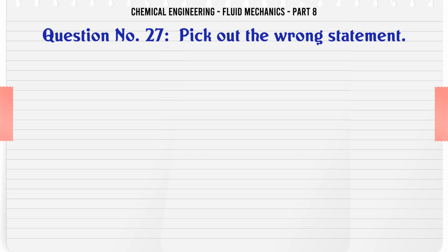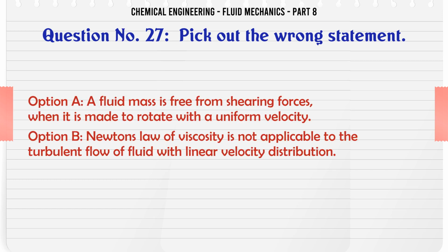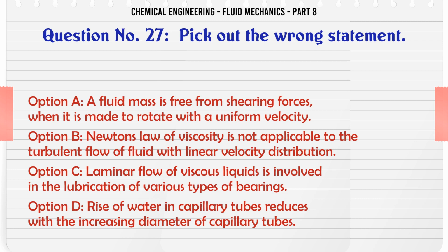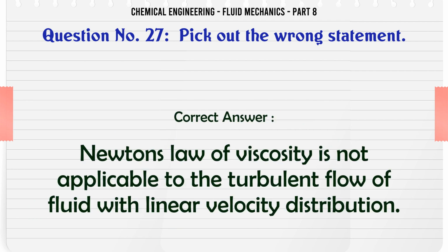Pick out the wrong statement. A. A fluid mass is free from shearing forces when it is made to rotate with a uniform velocity. B. Newton's law of viscosity is not applicable to the turbulent flow of fluid with linear velocity distribution. C. Laminar flow of viscous liquids is involved in the lubrication of various types of bearings. D. Rise of water in capillary tubes reduces with the increasing diameter of capillary tubes. The correct answer is Newton's law of viscosity is not applicable to the turbulent flow of fluid with linear velocity distribution.